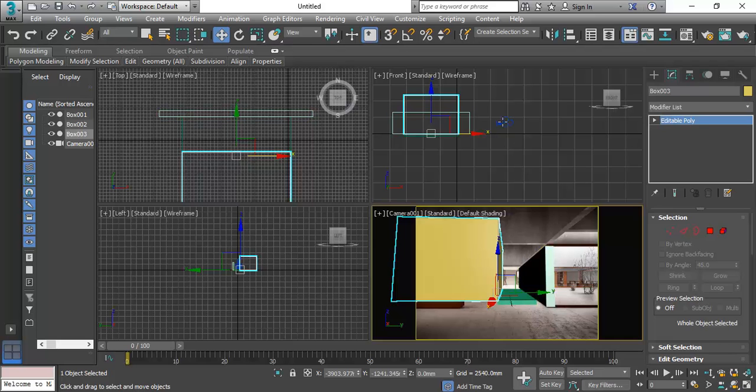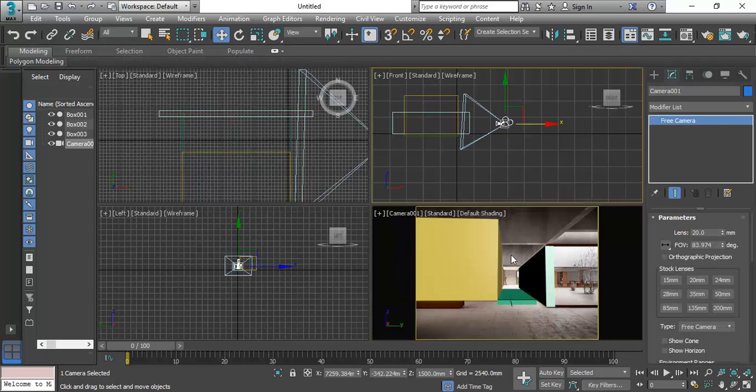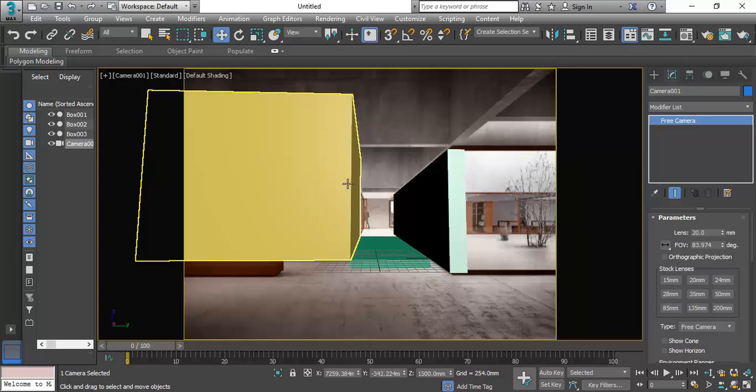But before I go any further, I'm going to have more of a look now at the camera, because you can see now that I've got some bigger objects. Let's maximise that so you can see it, that my vertical axes are not straight. And that's a bit of a no-no. So do you know what makes them tilt in perspective? What makes the vertical lines go at an angle? Do you know what sort of perspective that is? Sort of. It's to do with the camera. It's all to do with the camera. That's right. Yep, that's right. Exactly. The target is not straight.